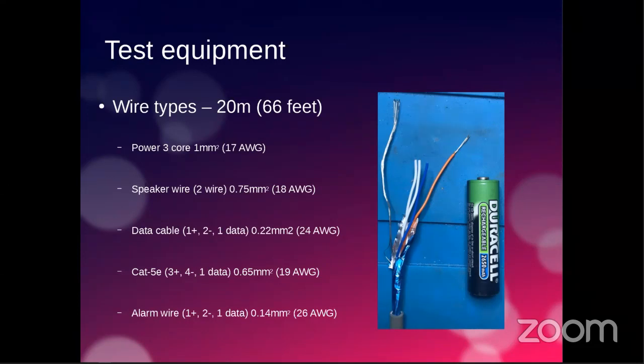So if you're not having problems with flickering, don't pull out and replace the resistor networks. They're fine. There's nothing wrong with them, right? It's just if you need that extra distance and you don't want to be buying several $5 null buffers, and you just like to increase the distance driven from the controller, then you might want to consider it. And you don't even need to replace all of them. You can just replace one or two of them. You only need to replace the ones that you need.